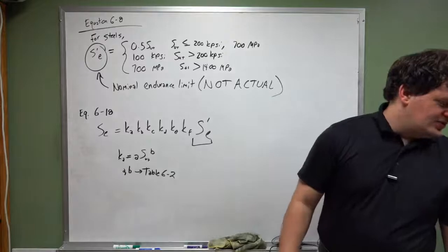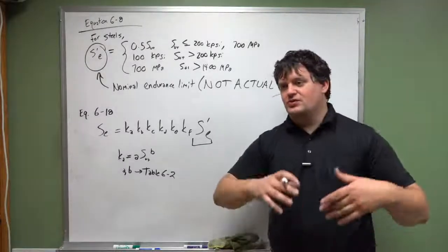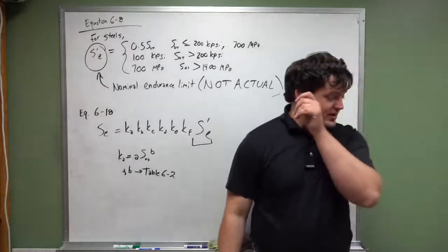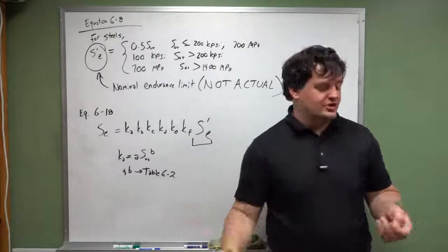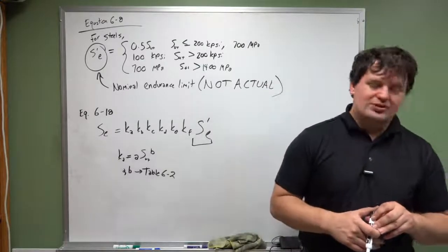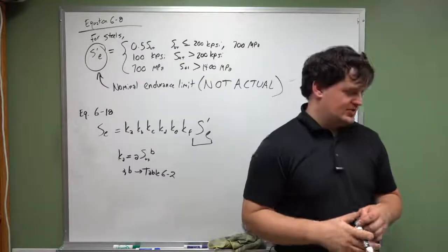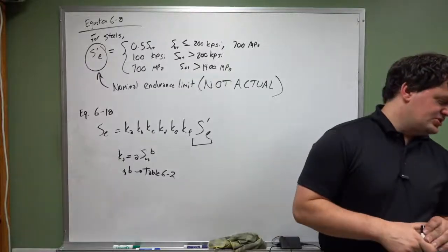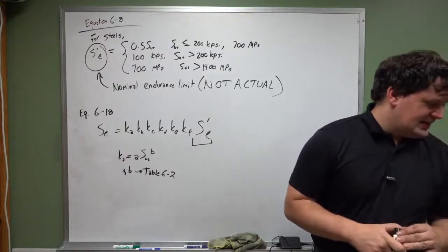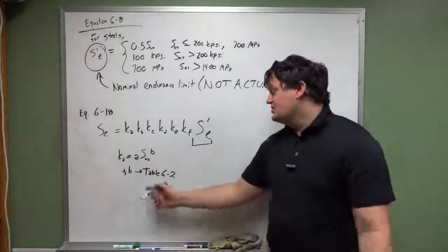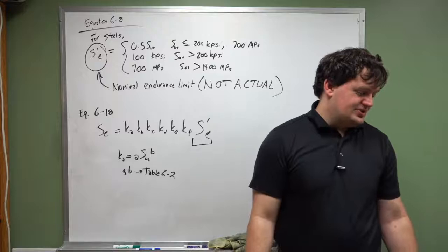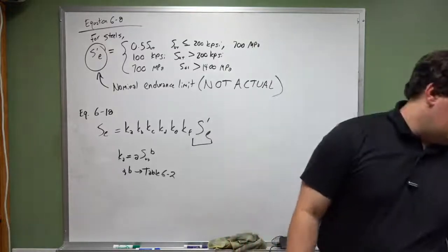You may have machined, which means it was drilled or it was planed. You have hot rolled, or you may have just a straight forged material. Depending on how it comes out, most of the time we're going to be dealing with hot rolled, parts coming straight out of it. Occasionally you'll deal with machined. But in that case, you just multiply these factors by this, plug it in for Ka. That's already a huge factor, and we haven't even talked about the number of cycles yet.